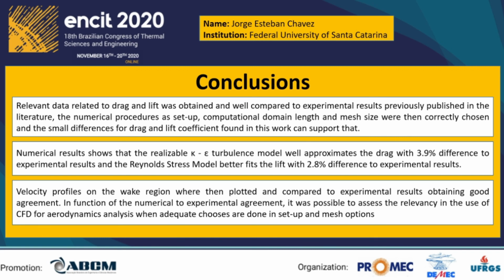Our second conclusion is that the numerical results show that the realizable K-epsilon turbulence model well approximates the drag with 3.9% difference to experimental results, and the Reynolds stress model better fits the lift with 2.8% difference to experimental results. Finally, the velocity profiles in the wake region were plotted and compared to experimental results, obtaining good agreement between the numerical and experimental results.